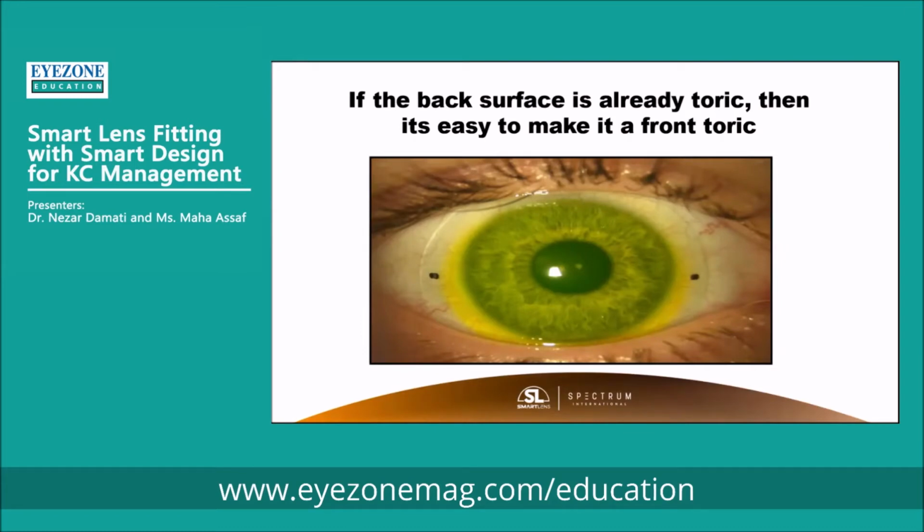And you have to decide if these lenses have a rotation or a stable rotation. In this part, you have to mention this is stable, and you have to mention the location of the orientation mark to take into consideration with the manufacturer people how to allocate it. It's very important to decide where the orientation mark is located.